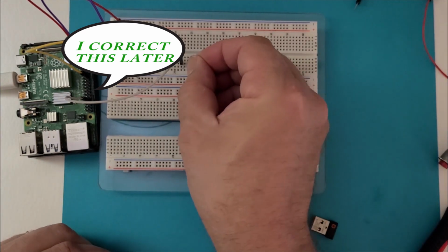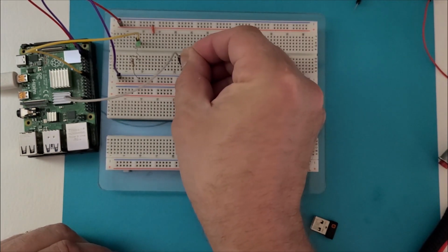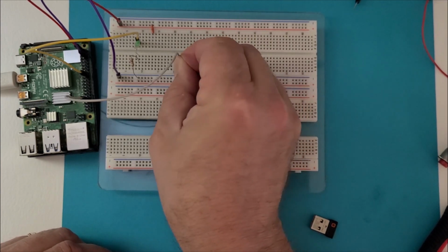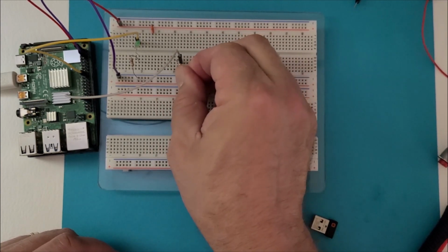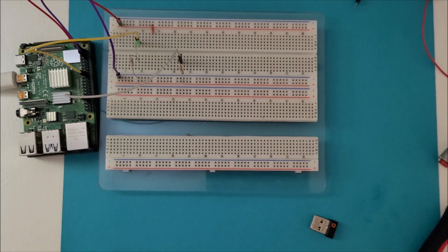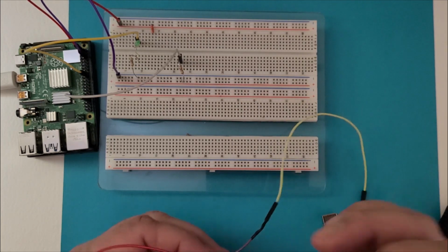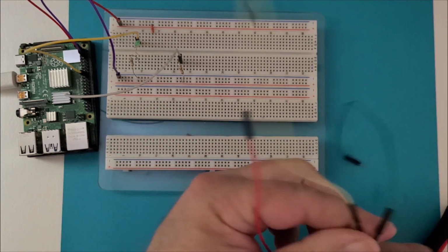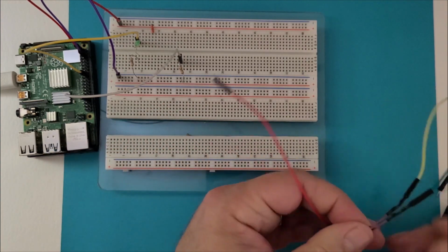Let's bring pin 36 over here to a spot along here, and we'll put in a resistor here. This is a 470 ohm resistor to ground on this. And that's just a pull down resistor and current limiting resistor for when we hook up our switch. Now this switch, the green one, is the center. It's got both a normally open and a normally closed.